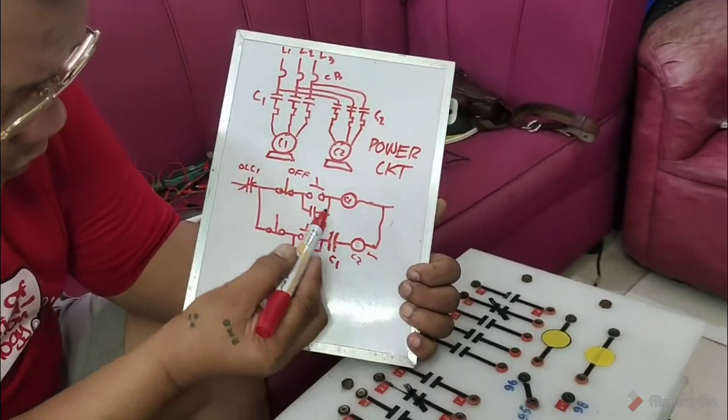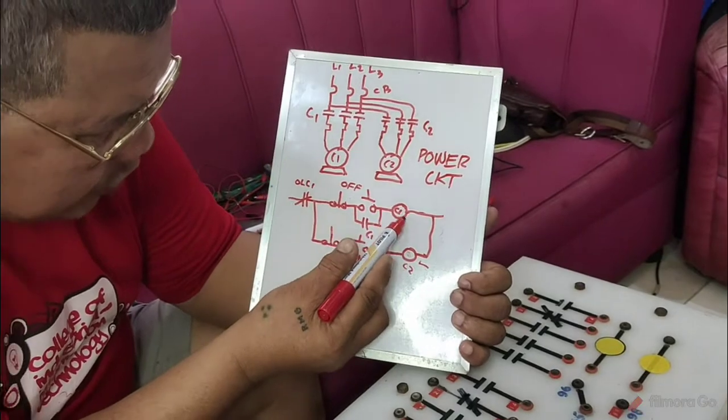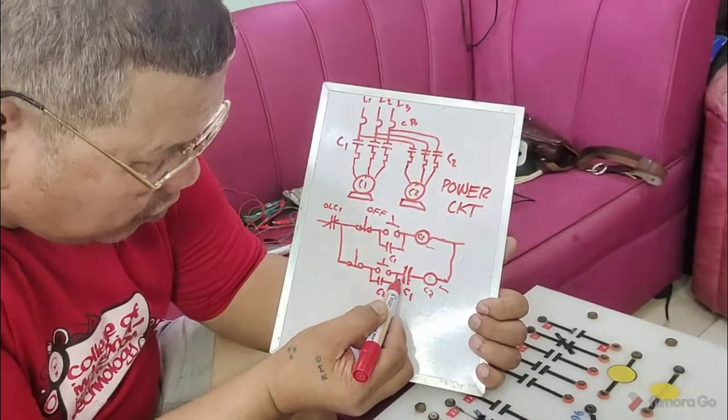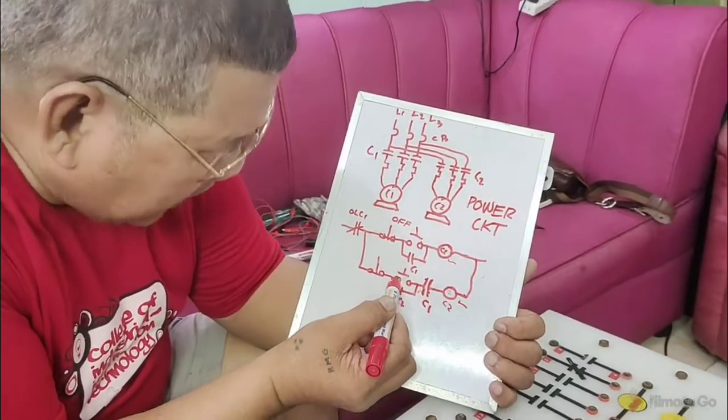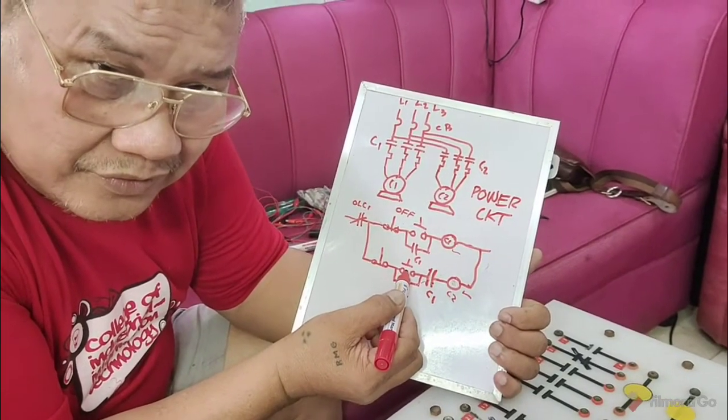So what will you do? Once you press the button here, this will energize. Of course, this will close. Then that's the time that you will switch on. Okay?